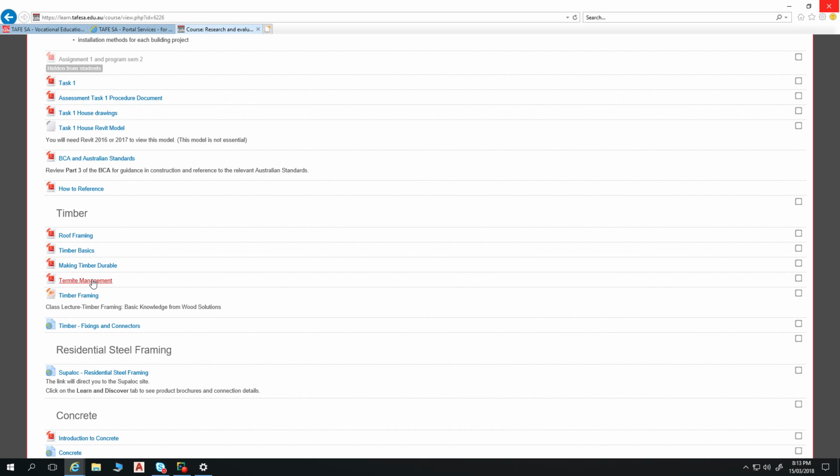Certainly we use LOSP treated timber in that scenario anyhow, being outside. But that's where it comes down to the designer thinking, okay, yes, the span tables enable the nail lamination of timber, but is it actually a good application of it? And if you decide to use an LVL, you can't, it's not very good outside.